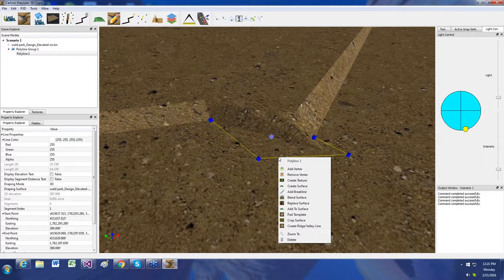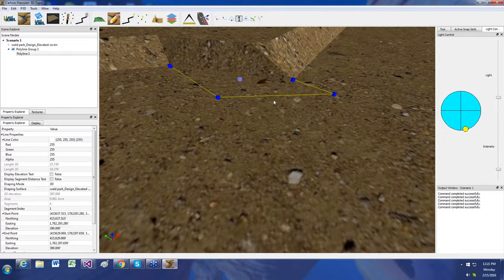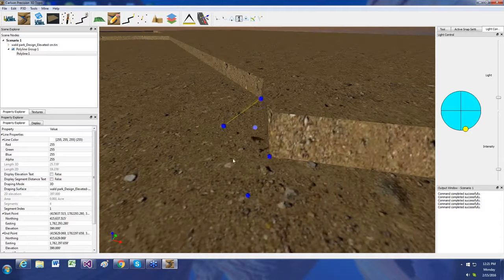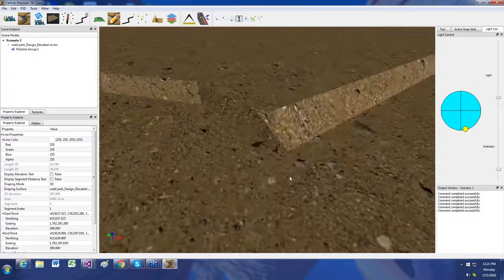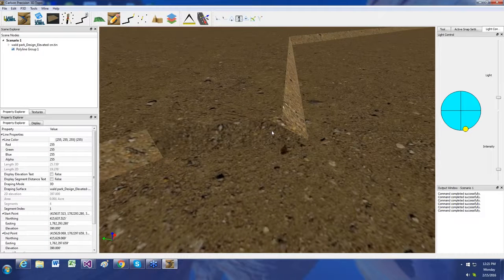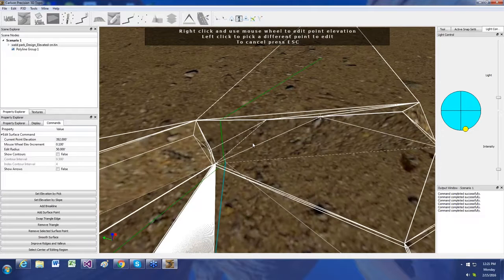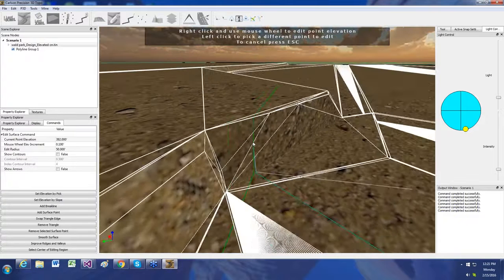While it's in 3D mode, the difference between blend and replace is that replace will not drape the polyline to the surface, and it will add it. So you get this vertical cutting sort of behavior, like that. So now I just sliced off that bad part, and certainly I can come back in now. I can re-edit the surface, and I can establish whether or not there's additional points that I want to keep.